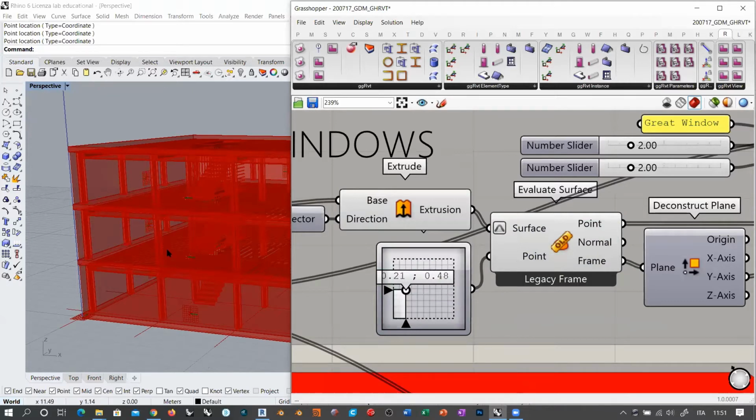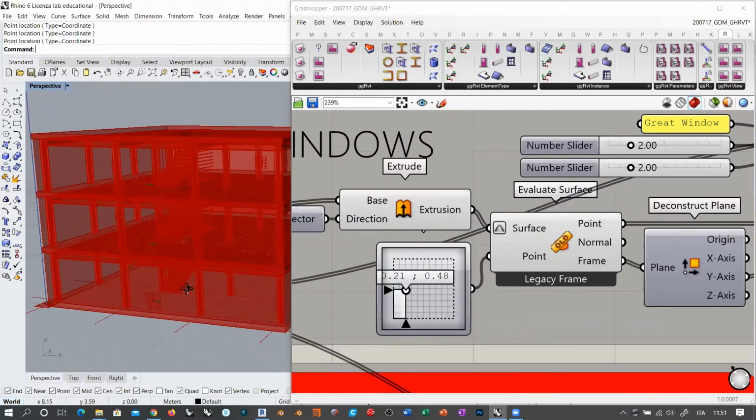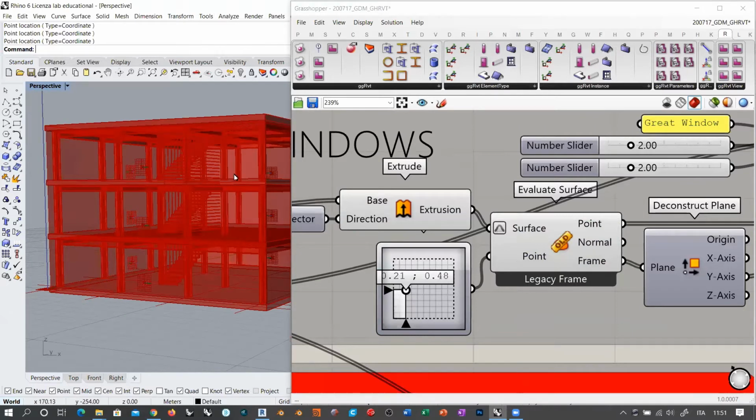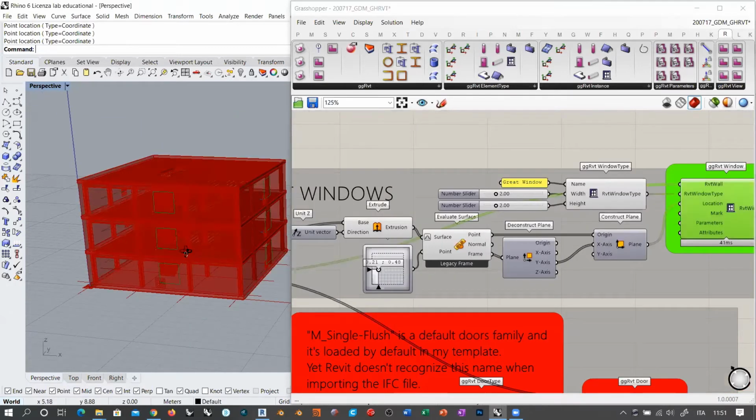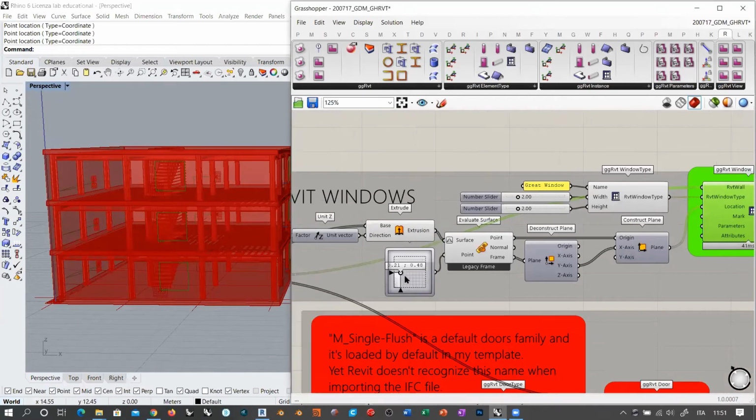So these are separated, so independent surfaces. We have 4 independent surfaces per level. And so we are reparameterizing each of these flat panels here. Okay, so they are rectangular surfaces. We are reparameterizing them, which means that for Grasshopper, in this moment, they measure 1 by 1, independently from the geometrical aspect. And we use this slider here to say, okay, I want to place the window. Let's activate this. I want to place the window using this parameter here.